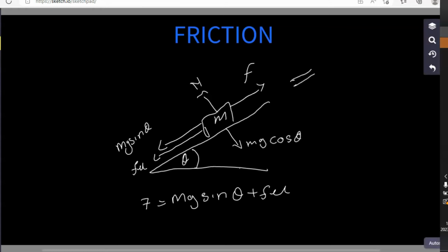And then we also have to equate the forces that are perpendicular, which will be normal reaction equals mg cos theta. This is theta. Remember, you don't have to cram these formulas. As long as you draw the correct structure and then say forces going up the slope are equal to forces going down the slope, because this is not a standard equation.